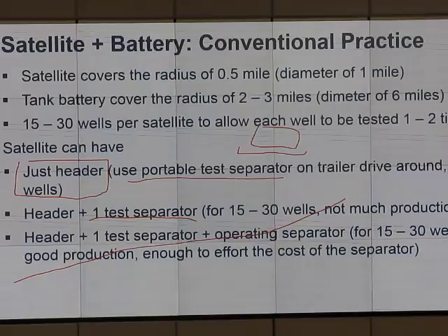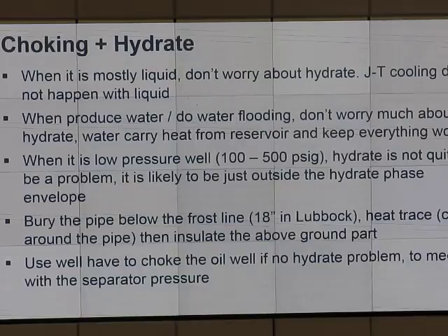Do we have to worry about hydrate? In your project, I think one of the projects has a lot of water flooding and a lot of oil, right? Okay. Here's the rule of thumb. Choking and hydrate problem. When it is mostly liquid, don't worry about the hydrate.